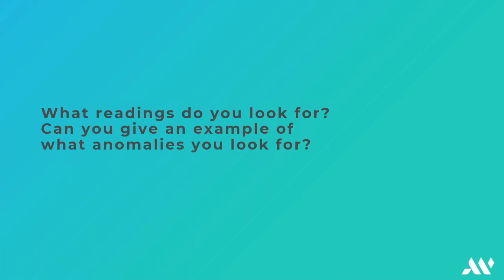Yeah, there's definitely going to be a little bit of crossover from some of the comments that Chris made on that last question. But what I always keep in the back of my head when I'm doing any analysis is, what are my frequencies of interest? That breaks down to observing what is of amplitude within your spectral content, and what frequency the impacting within the time waveform is spaced at.